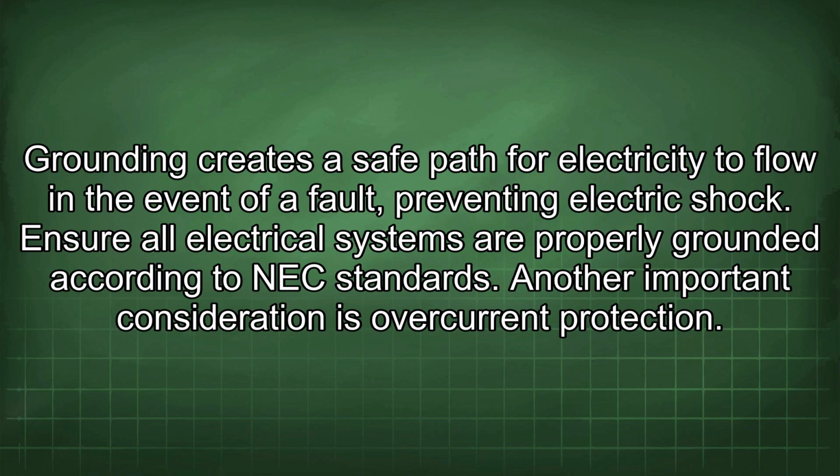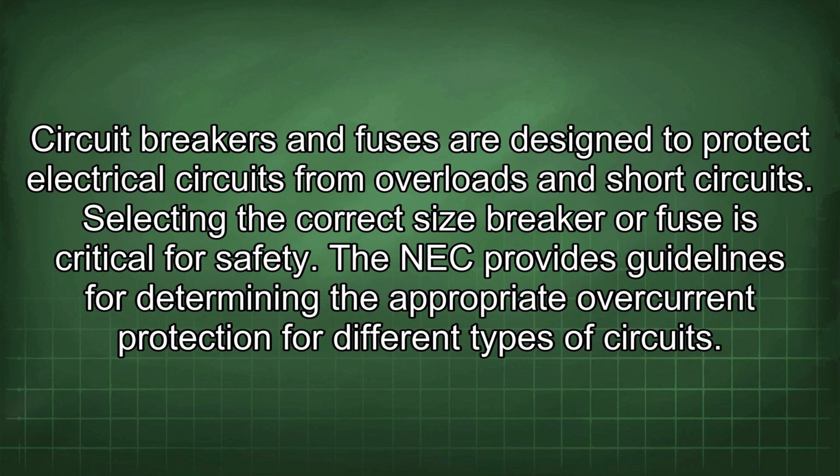Another important consideration is overcurrent protection. Circuit breakers and fuses are designed to protect electrical circuits from overloads and short circuits. Selecting the correct size breaker or fuse is critical for safety. The NEC provides guidelines for determining the appropriate overcurrent protection for different types of circuits.